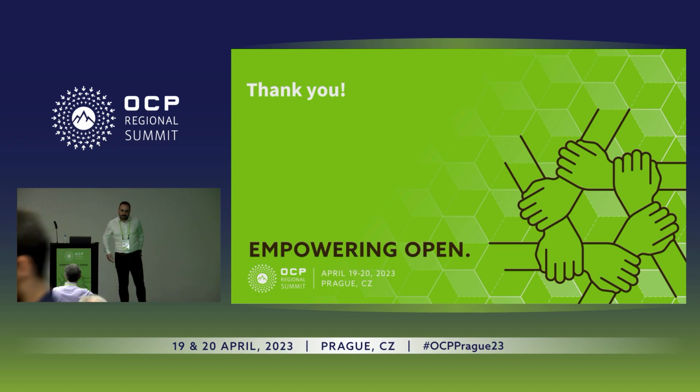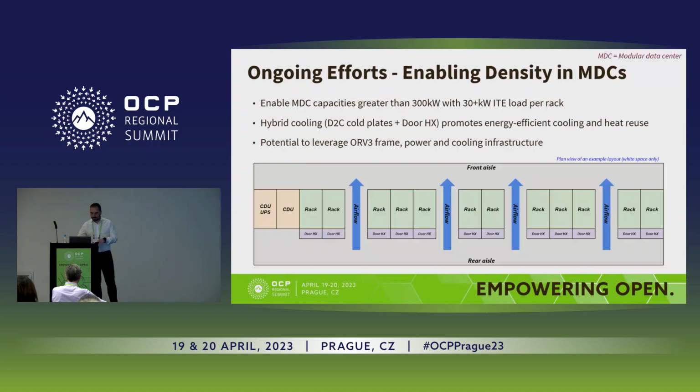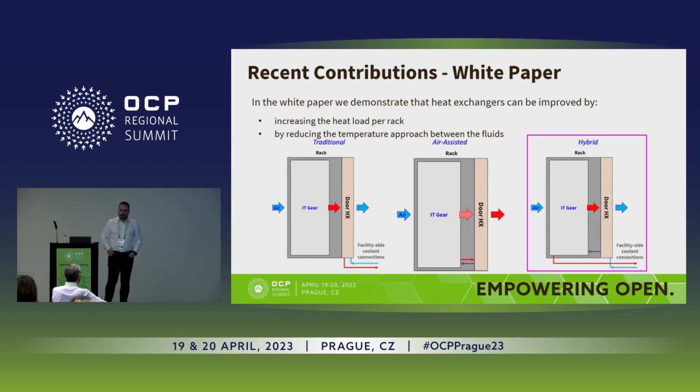So with the rear door, there are two solutions, aren't there? Depends whether you've got cold plate in the loop. So there's what's called an active rear door and a passive rear door, isn't there? Is the group considering the differences between these, where you have fans in the door itself? I think there are relative merits of one versus the other. But if you've got cold plates in the loop, and that's always an issue when you've got cold plates, should you have two water connections because of the temperatures of operation, or should you put them in series? I wondered if the group was looking at the differences between passive and active rear doors.